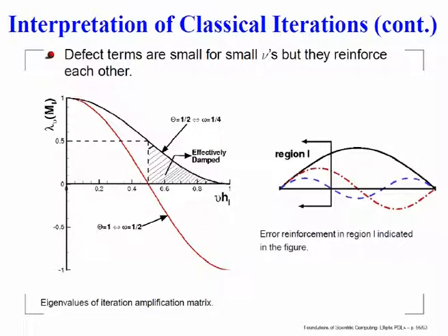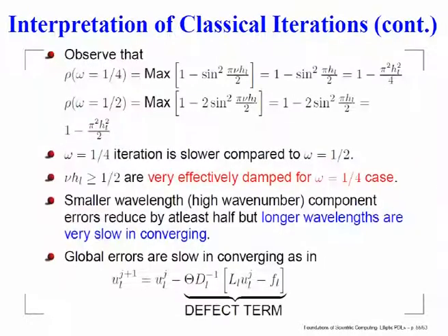So that's what we say, that when we look at the convergence history, we might see the solution without any under relaxation would do better than the one done with this. Whereas we have also noticed that with the under relaxation, we could remove the error component which was at the highest wave number range, right?